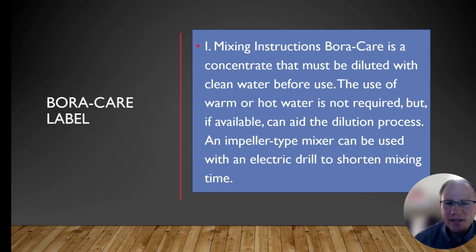Let's look at the mixing instructions on a Boracare label. Boracare is a concentrate that must be diluted with clean water before use. The use of warm or hot water is not required, but if available, can aid the dilution process. An impeller type of mixer can be used with an electric drill to shorten mixing time. This is a really big deal.